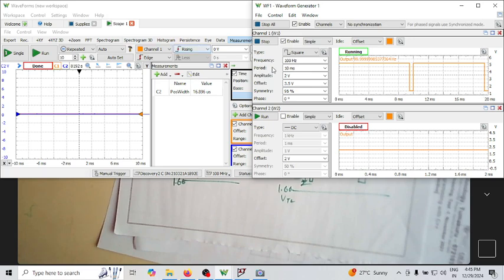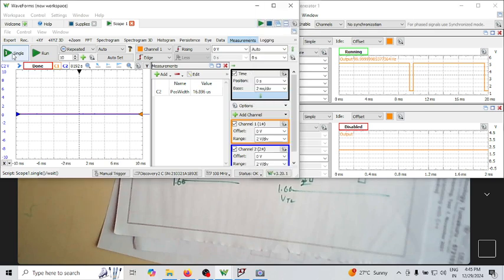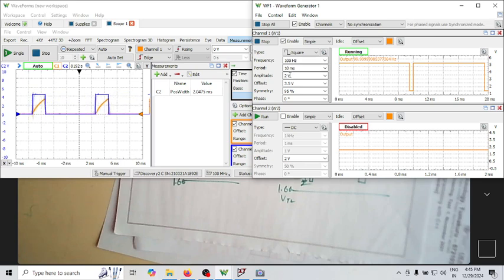okay, what I'll do, I'll just run it now. You can see now, are you getting the output? Let me just keep running it and show you what happens if it is 1.5 and if it is 2. If it is 1.5 it is off. If it is 1 it is off because it is at 2.5 volt and it is not less than VTL, the trigger signal is not less than 1.6.